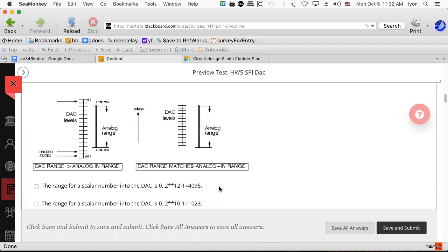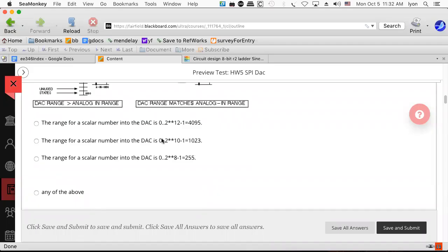That's good. Can you make it also so that it goes from 0 to 1023? And the answer is yes. Yeah, you could. Because why? Because you just need the least significant 10 bits. Or if you like, use the most significant 10 bits and ignore the rest.